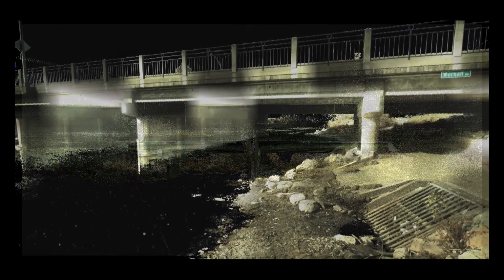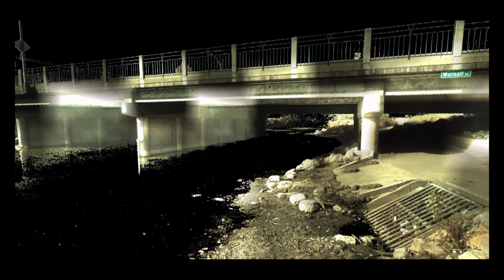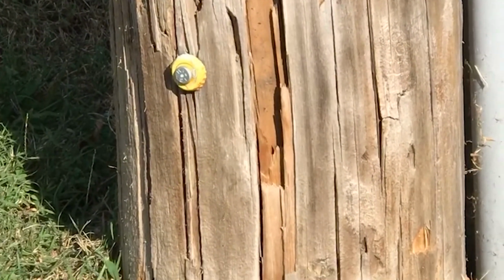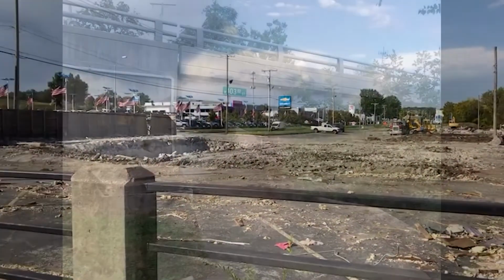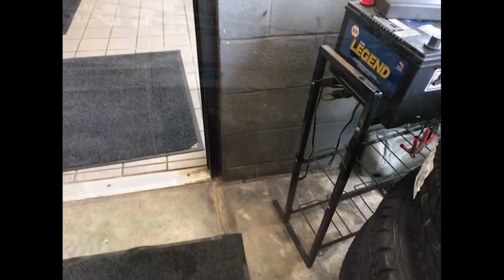Historic information on the flooding, which included old reports. It also includes photographs of high water marks so that we know where we're calibrating to, so we're making sure that the results of our modeling meets what was actually physically observed.